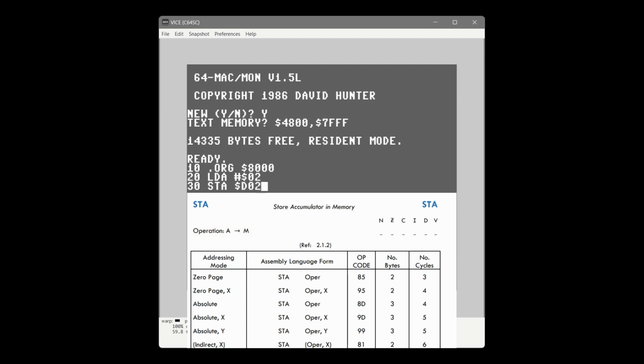So we're going to type in the memory address D020. This is what's called an absolute address because we gave it a literal spot in memory. And the absolute address opcode is 8D. So when it gets turned into machine language code, that's the value that's going to be stored in memory. And then next to it, you might be thinking it's going to be D0 and 20 for the next 2 bytes, but the 6502 architecture is known as little endian, and it actually puts the smaller part of the number first and then the bigger part later. So this is what it would look like when it's assembled.